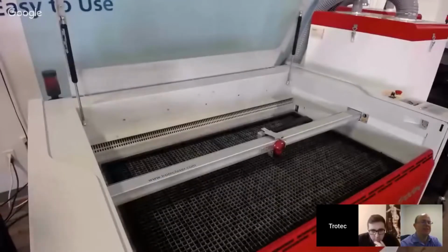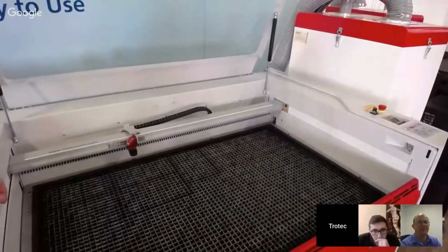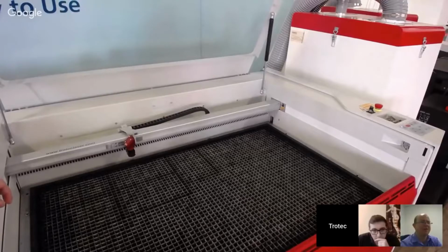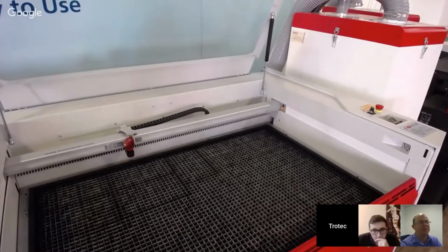So you end up actually getting some of that smoke sticking to your engraved area, which is what we don't want. Many people, I'm sure, if you've ever tried to engrave red and white plastic, that's always the nightmare combination, because if you're engraving top down, you end up with pink engraving instead of white. And that's because that red smoke has gone in and it's stuck to the sticky white inside material, and it's turned it pink on you. So to avoid that, we engrave bottom up. So what it does now is it's sucking that red smoke across red surface material, and it doesn't color it anymore. So that's how you get that nice white engraving.